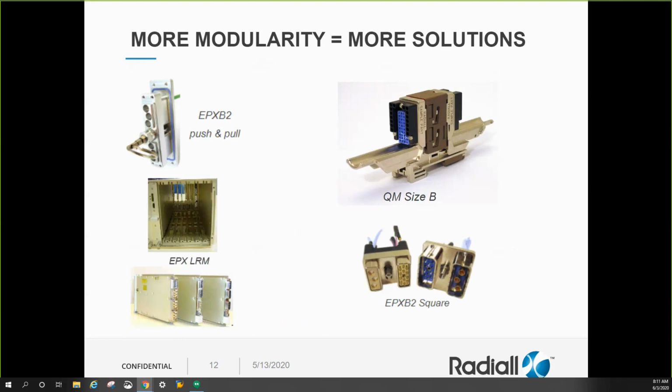Another rectangular design in the works is for line replaceable modules, or LRMs. These systems are becoming more commonplace as they eliminate the traditional step of first removing the system-level avionics blocks, or LRU, that we were talking about earlier, and sending it back to the depot for eventual replacement of a pluggable circuit board. By designing a system around the concept of LRMs and holding spares at the LRM level instead of at the box level, the cost, volume, and weight of spare holdings can be reduced.